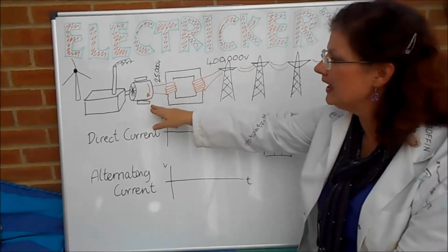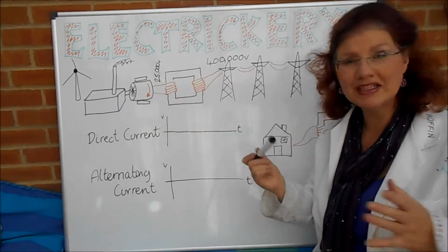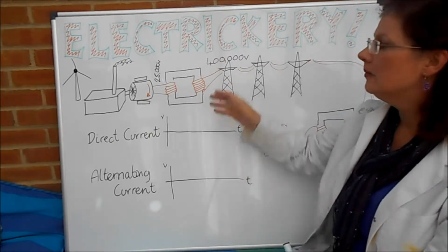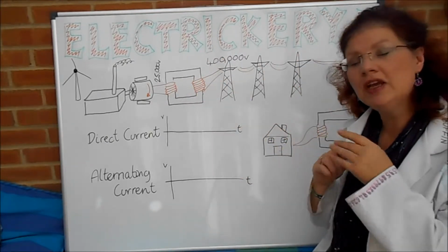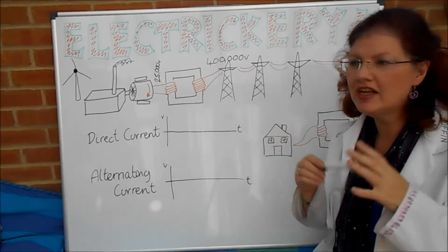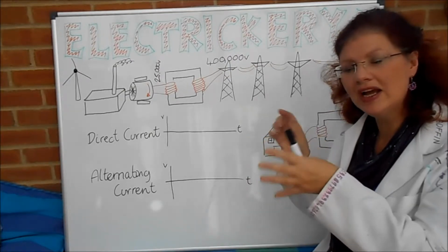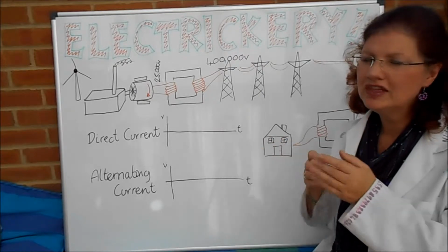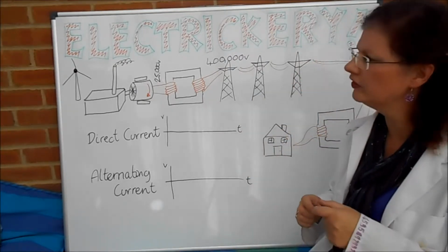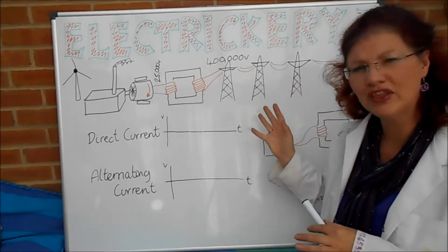So we've got it coming out of your power station through a transformer, and again if you look in the electromagnetism series it'll tell you all about transformers and how these coils work and everything like that. But just bear in mind that here it's the same kind of thing as you may have at home, but usually those will be step down transformers, things like fairy lights or scale electric cars and things. They have transformers to take your household electricity, which is at say 230 or 110 volts, and to transform it down into something like 12 volts. Here we're transforming it up from 25,000 to 400,000 volts.